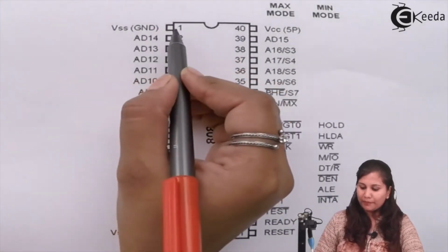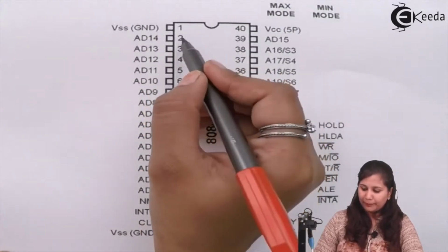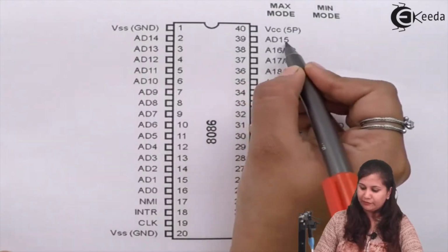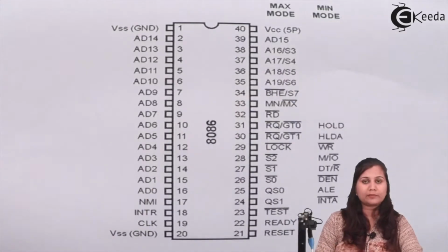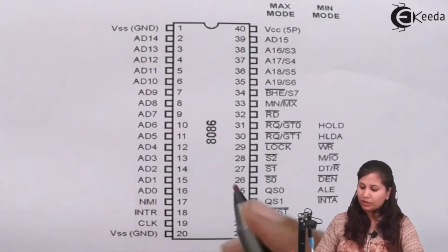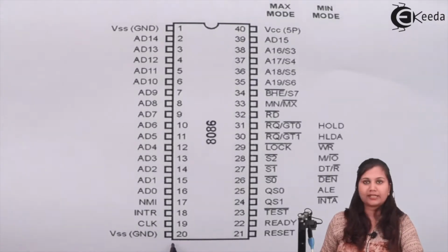So let us see. On pin number 1, we have the VSS, or the ground. From pin number 2 to pin number 16, we have the address and data bus AD0 to AD14. Then we have AD15 here, and A16, 17, 18 and 19. So the address bus is of 20 bits in the 8086 microprocessor, so we have 20 address lines starting from AD0 to A19. Then we have NMI, INTR, clock, and again VSS, ground. We have two connections for the ground.